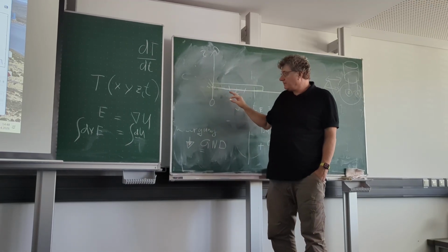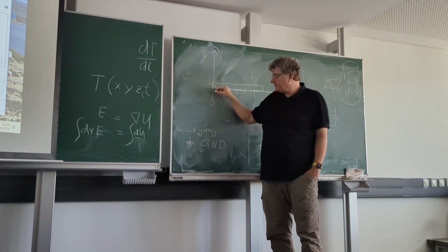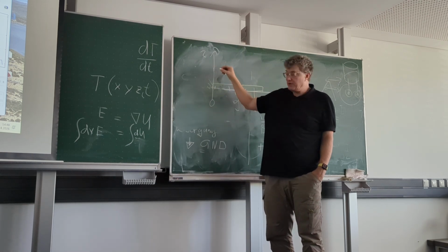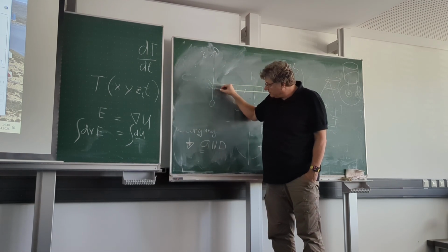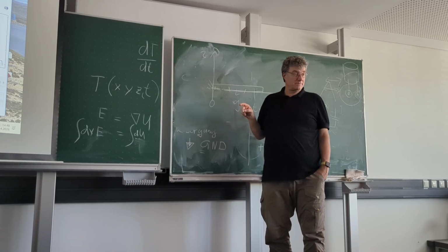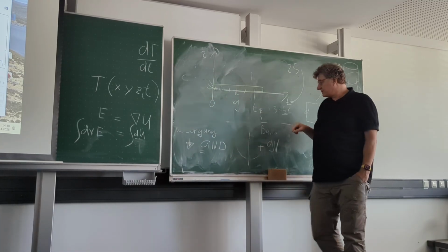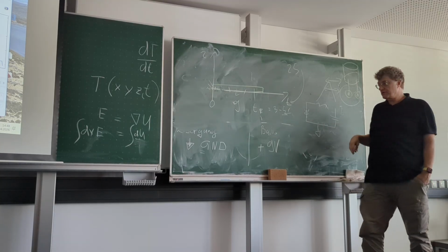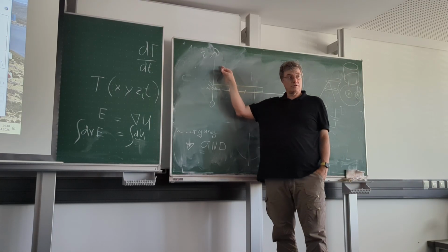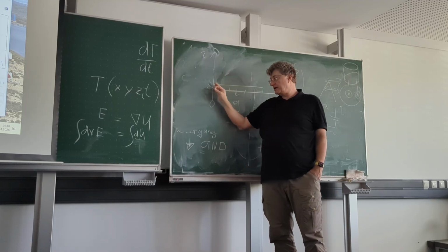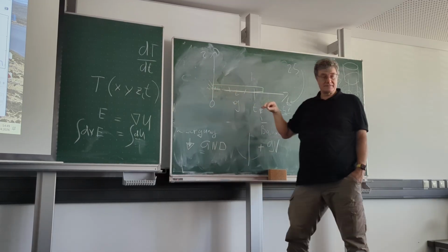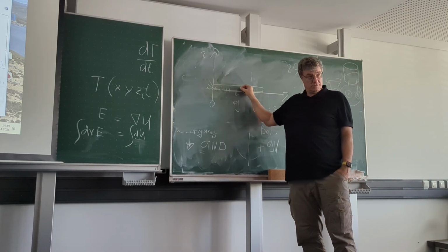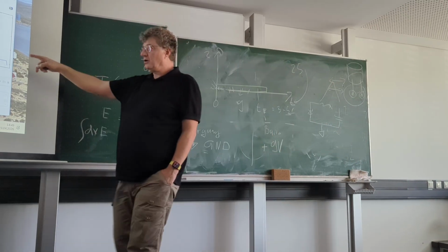And then the program has various algorithms to see if things change fast. For example, if in the beginning it would rise very quickly, it has to do very small time steps. So the time steps are actually not set by the fact that we put 1 millisecond, that is just an indicator. It has internal algorithms to check what the result is and then starts doing simulations very carefully. If it realizes things don't change very fast anymore, it can do larger steps. So this is basically what you see here.